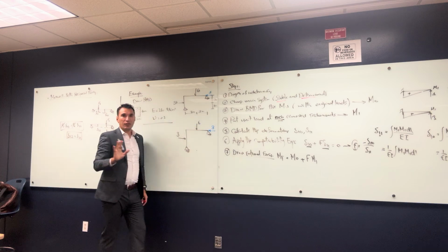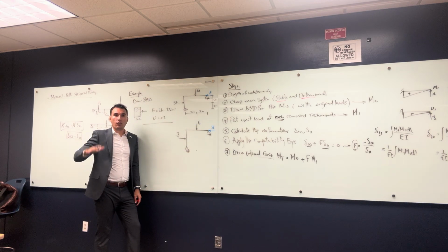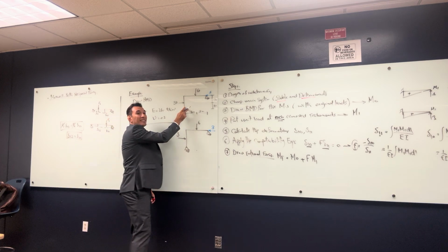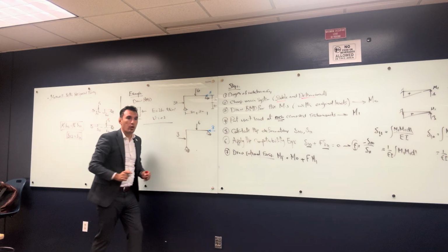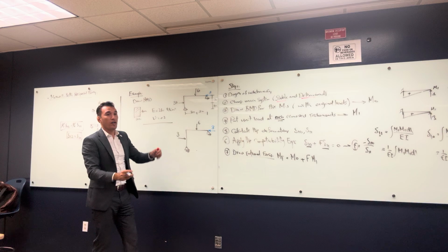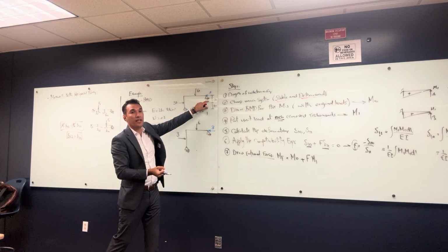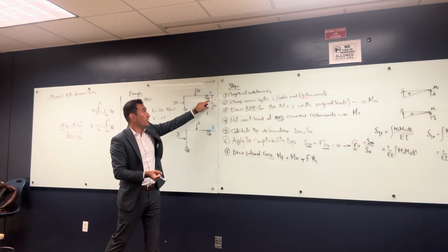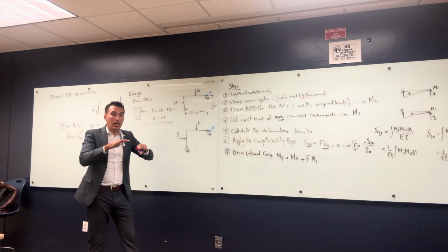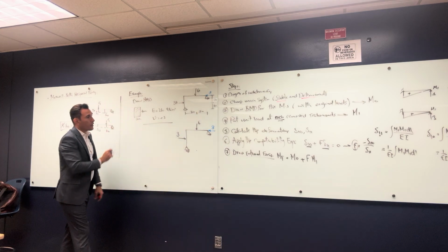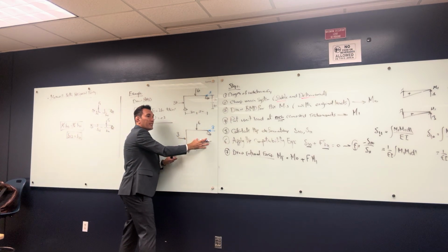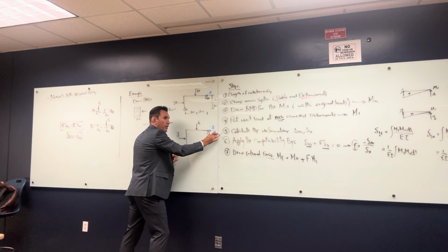No. Is it gonna be less or bigger? Less. Why? Because this is gonna get some contribution from the X. You are pushing this frame. This one is gonna absorb some horizontal reaction and this one is gonna absorb some horizontal reaction. So I believe that this one is gonna be a little bit less. Okay, but right now, since we made this main system, this one is taking all the 3.